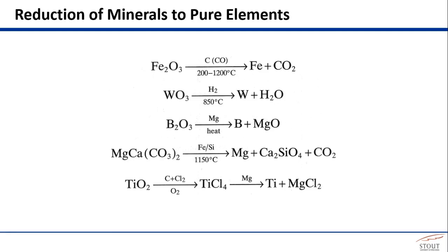And depending on the thermodynamics of the system, often, no problem. It donates the electrons from carbon, in this case, to the metal, so it can rip away the oxygen and make carbon monoxide or dioxide eventually as a byproduct, because carbon monoxide as a gas, entropically and enthalpically, is more favored than the oxide. It lowers its overall energy by doing this. So using the oxygen from the metal oxide as your oxygen source is really the heart of the smelting operation.